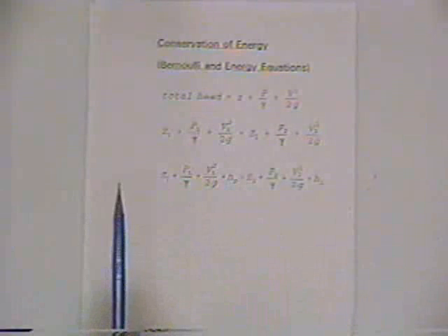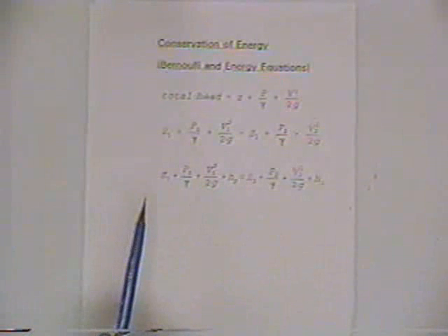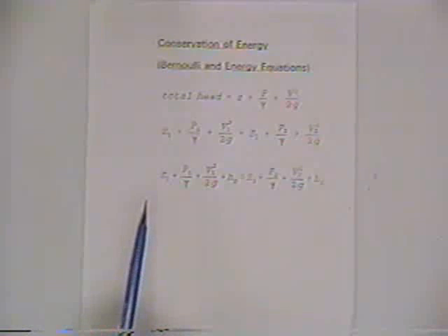And so the basic concept of energy is that, in engineering applications, we like to talk in terms of head. And so we went to the basic derivation of the Euler equation. We would derive energy per unit mass, and then we'd divide by g, and we'd get energy per unit weight. And so that's convenient to work with, because if you've got energy in Newton meters per unit weight, Newton meters per Newton, that gives you head in meters, which is quite convenient.